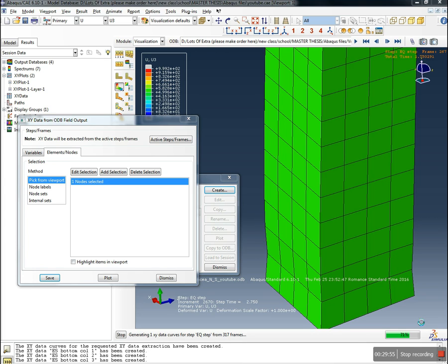But obviously you have to use stirrups everywhere because that's how reinforced concrete frames work. But what I want to say is that the stirrups normally for the bottom column are much closer one to each other. But this of course comes from some design consideration.